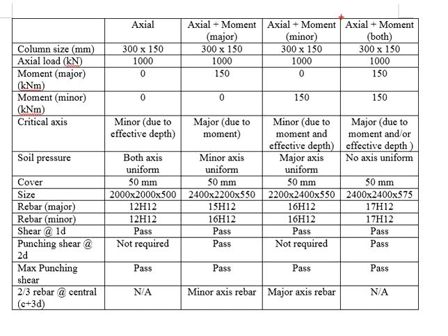And then how about the absolute plus moment in both axes? In this case, we use the same magnitude of the moment. This might not be the case. Sometimes it can be a greater moment in the major axis. Sometimes it can be a greater moment in the minor axis. If two sides have the same moment, most likely it's going to end up a square section. If either side has a greater moment, it may end up with a rectangular section in the direction where